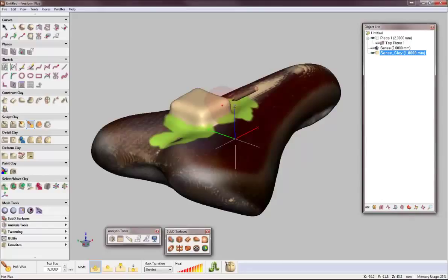The Freeform product extends CAD in a different way. CAD packages are very good at modeling and designing in a prismatic, feature-based world. Well, there are a lot of different products on the market that need to be manufactured that you maybe don't need history on, or are very organic to a point where the history can get in the way of a design process. So, for example, toys in the toy aisle at the store, very difficult to model something like that in a CAD package. So what you would use is Freeform alongside the CAD package to model all the organic shapes.